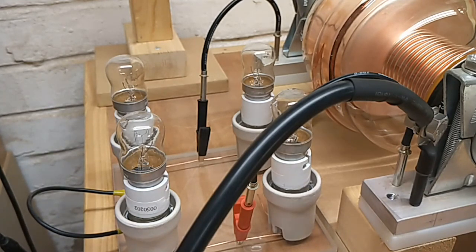so we can get to our low loss transmission condition when both transmitter and receiver TMT are optimally tuned for the transverse mode in interaction with the standing wave for the longitudinal mode, and then we can get maximum power transferred into the receiver load. We haven't been able to create that condition in this setup. So what I'm going to do is to try to assist getting more power into the receiver load.